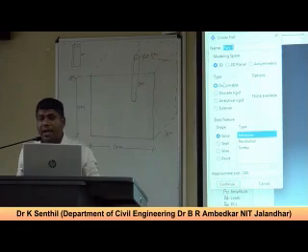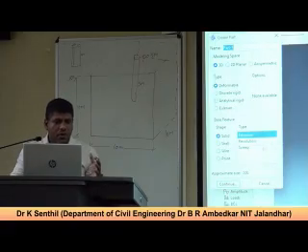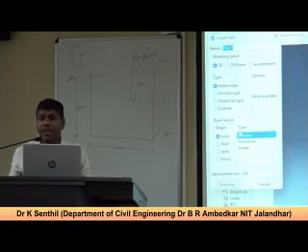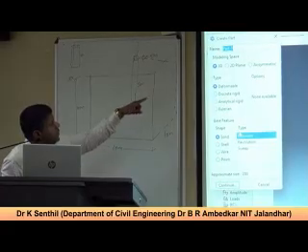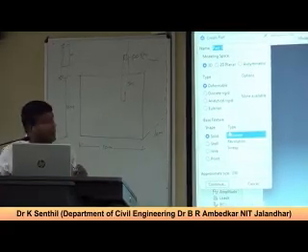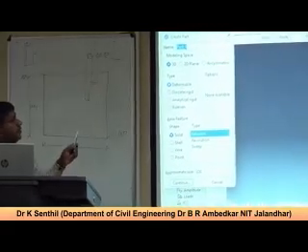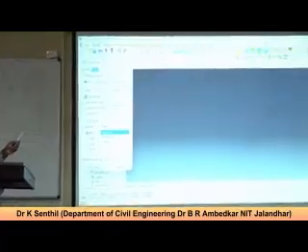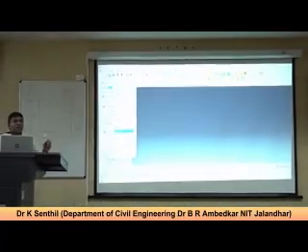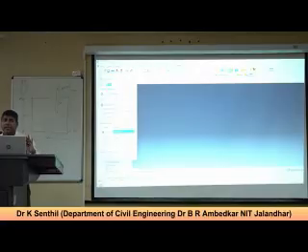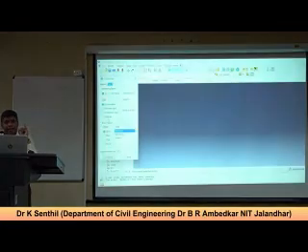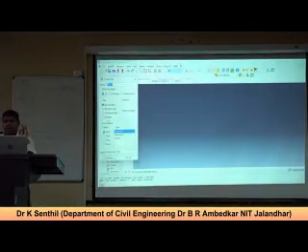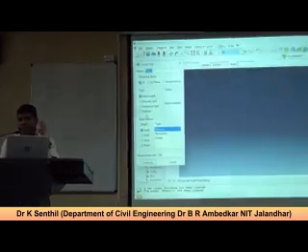And we should have an idea about the coordinate system. Of course, most of you studied FEM, so you might be quite familiar with the coordinate systems. Now you go for this 3D, and if you look here, there is deformable, discrete rigid, analytical rigid, Eulerian model. We actually have three different specific analyses: Eulerian, Lagrangian, and arbitrary Eulerian Lagrangian model. These three things we considered.